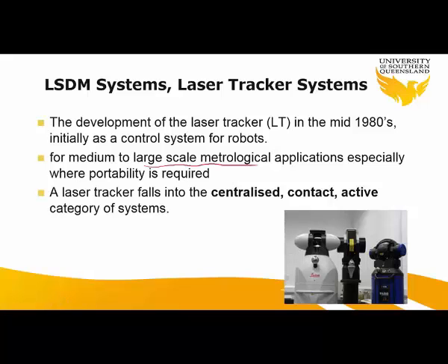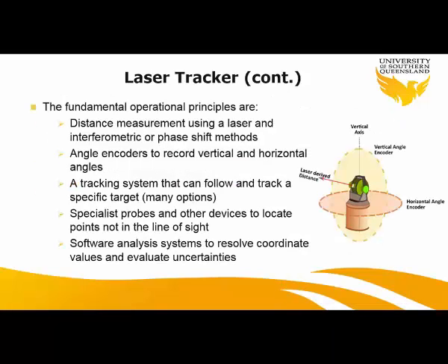It falls into the category of centralized, contact, and active system. If I'm saying centralized, it's a one-to-one measurement system. It is contact, so you need to have a target, and it's an active system because it's using the laser. It emits the signal itself, and it's reflecting back and measuring the coordinates or distance. So let's start with how it's working.